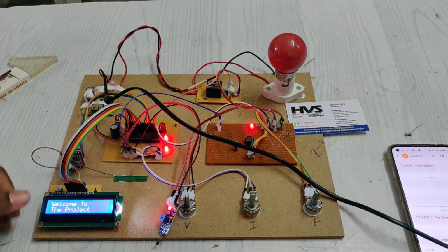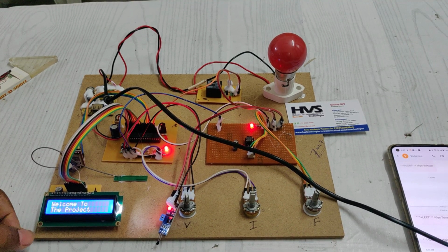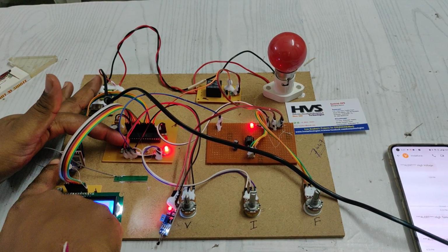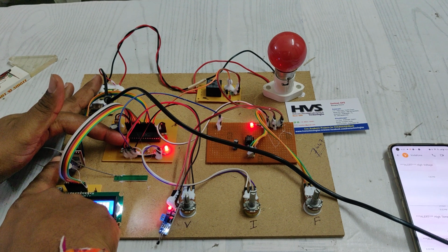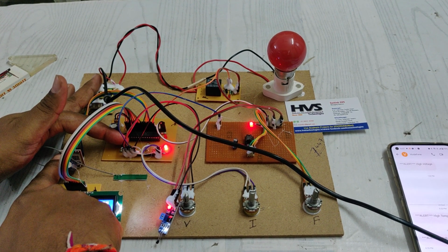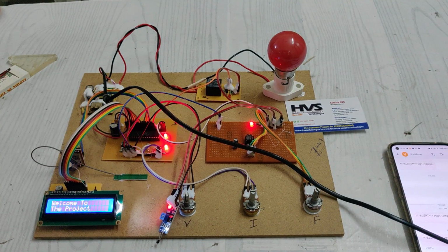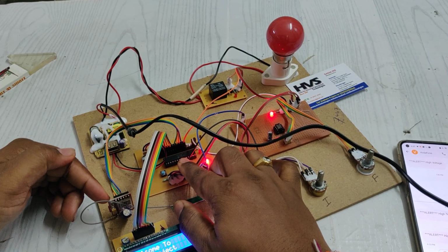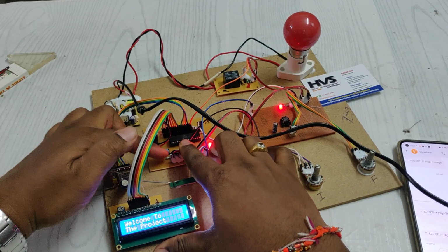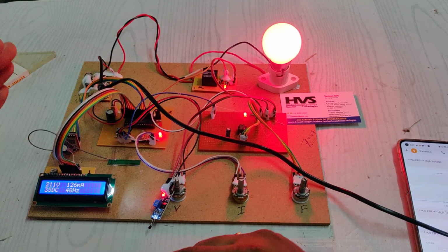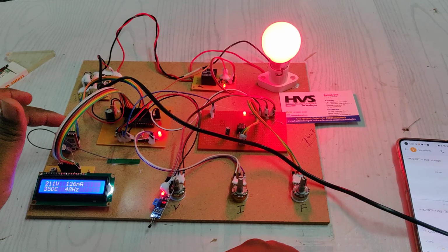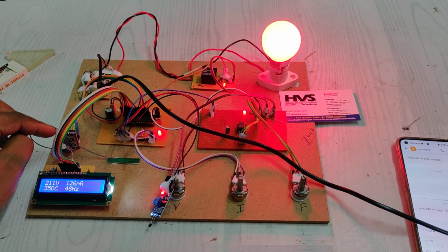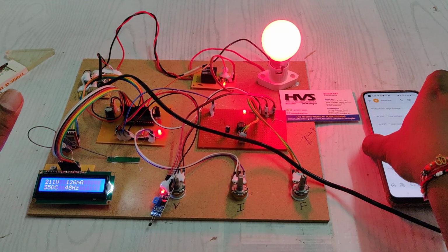When you switch on the power supply, a welcome message is displayed on the LCD screen. After that, wait until the light on the GSM module, which is blinking very fast initially, slows down. Right now it has slowed down. After this slowdown, release the switch. This is a reset switch. Press and hold until the GSM modem LED blinks slowly. Once it blinks very slowly, release the switch. That indication means we are holding the microcontroller until the GSM modem gets the signal. Once the GSM modem gets the signal, the LED on the GSM module will blink slowly. Now everything is normal.